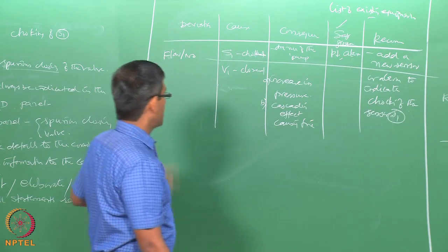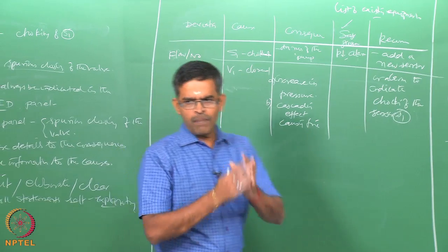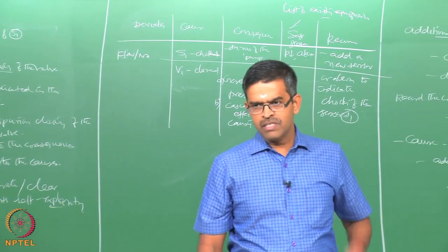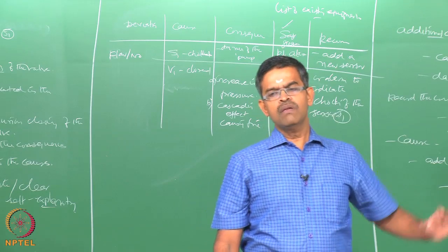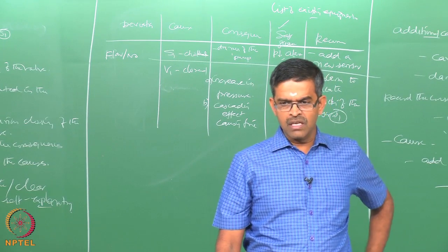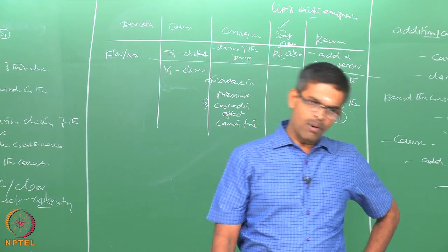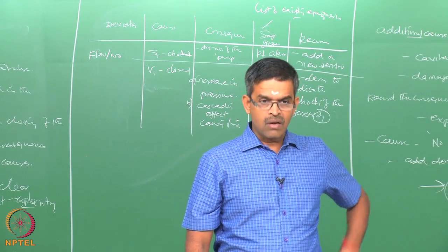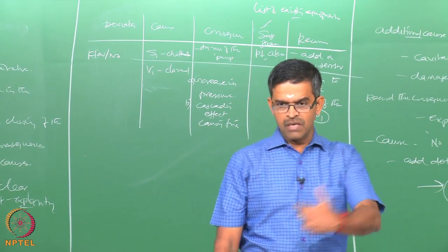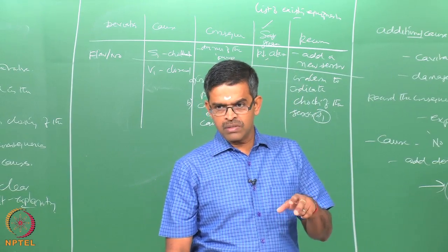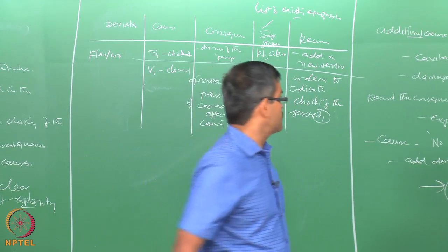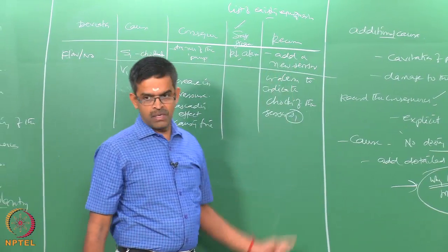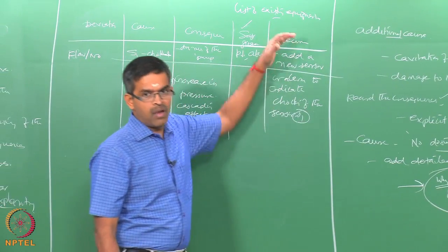Therefore, friends, a Hazop report is a very elaborate report written on diagnosing a specific flow line, which indicates all possible design intents and deviations, the reasons for the deviations, which we call causes, and the consequences which are the outcome of these deviations. It also shows how these consequences are addressed in the design through existing safeguards, and what you want to recommend in the hierarchy, in the priority.